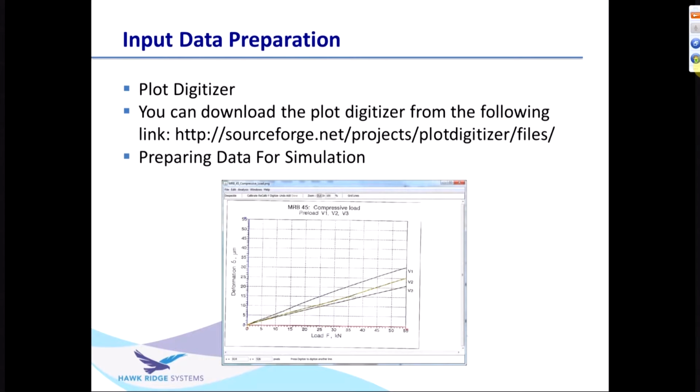So now we needed to prepare the data for simulation in order to create usable inputs to define our spring connectors. So Ingersoll provided again these data sheets, and the linear rail data showed basically the deformation as a function of the load being applied, and that data essentially needed to be turned into a stiffness input for defining the spring connectors.